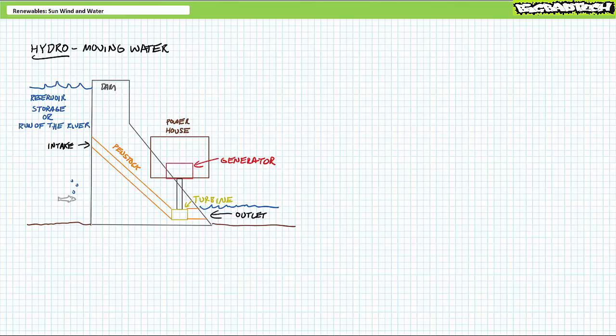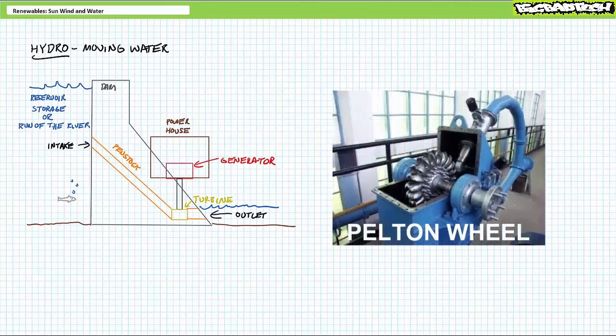I should note there are numerous alternate configurations for hydropower facilities and turbines that are often reflective of scale, head, and flow for a particular site. A popular design for smaller hydropower facilities is a Pelton wheel style turbine, which uses a nozzle to direct pressurized flow onto a wheel with buckets, called impulse blades, affixed to the perimeter.